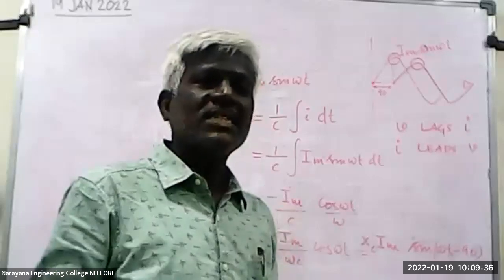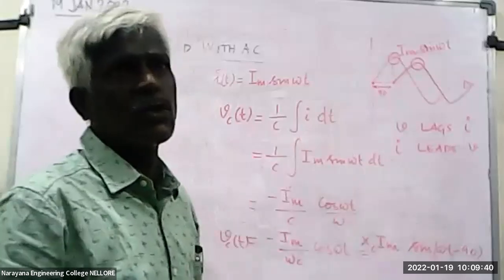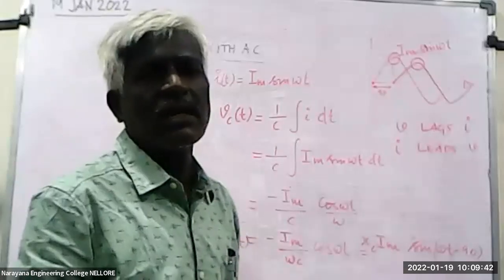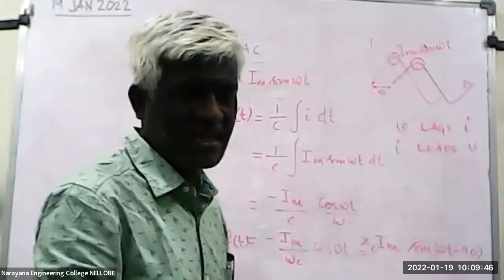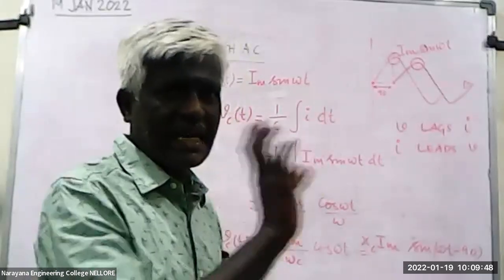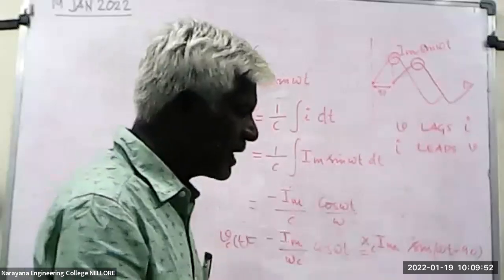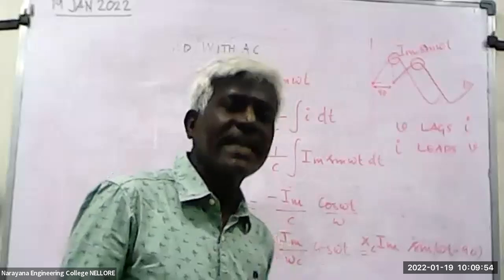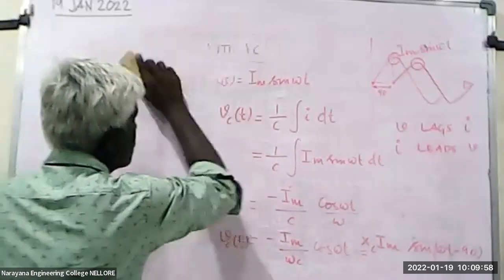So you add that kind of a panel intentionally. When you go to a power plant or any control room, you can see a panel called the power factor correction panel. You open that, and you see only capacitance. So they add capacitance as loads so that they lead the current, thereby making the power factor unity. Okay. Is that okay?